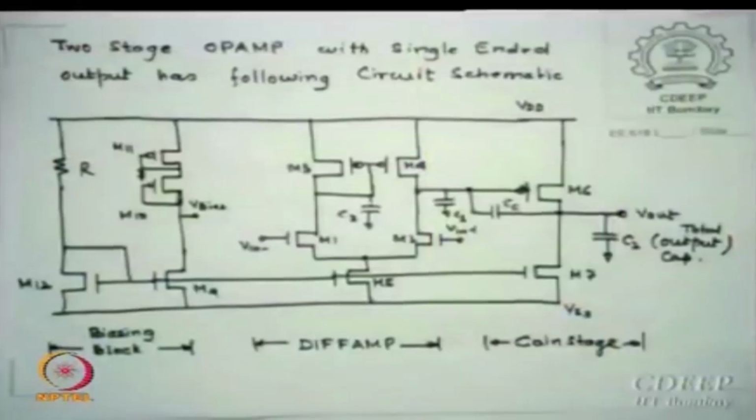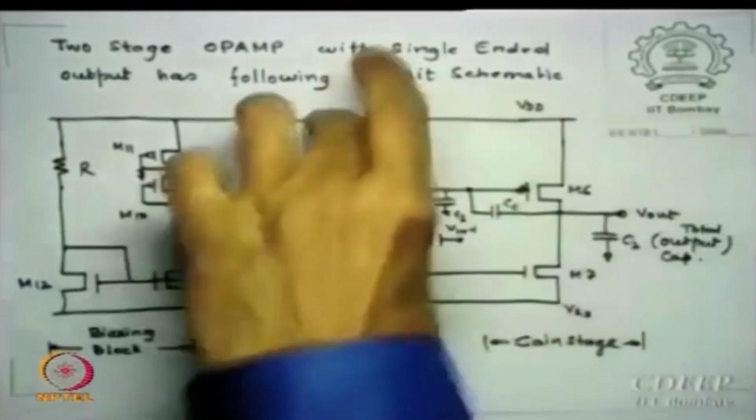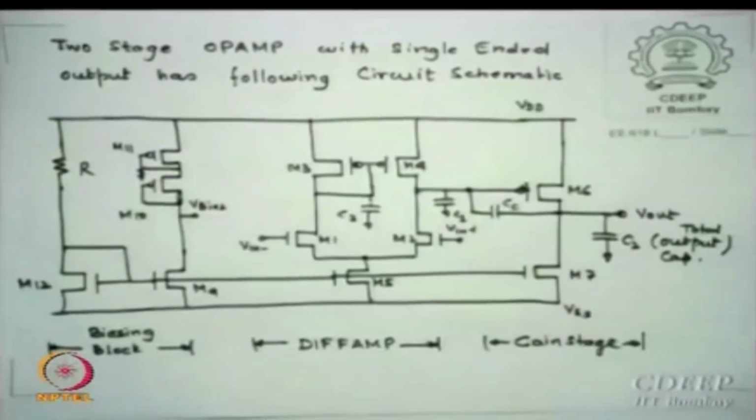Fine, because I am asking for more swing. See, my worry is how much gain I am allowed. So larger input swing is better, and with that the devices also work, fantastic. So if we have calculated 2 volts, and it becomes 2.2 volts, I am fair enough. It will still work, as long as this condition is satisfied. I am least bothered about it. The saturation condition should not be defeated by me.